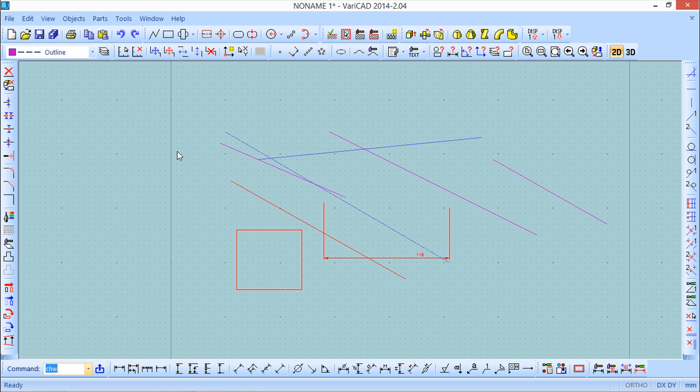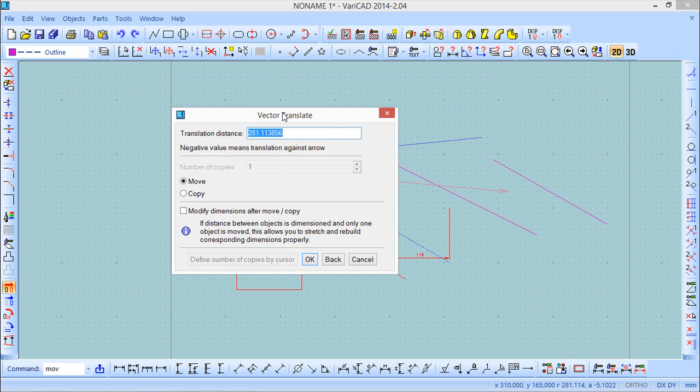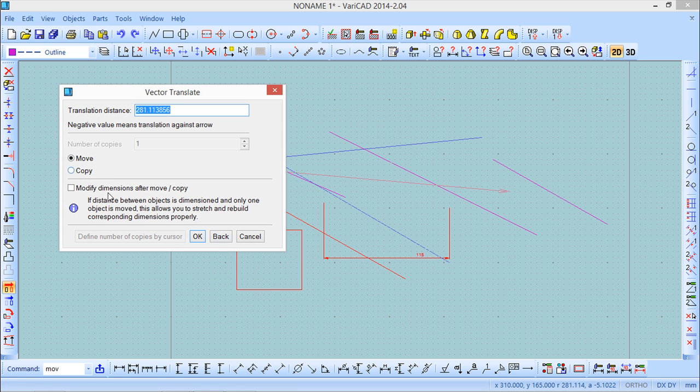But the purpose of this command, in fact, is that as layers are a possibility to organize information, worksets are another possibility. So let us try to do something that we still did not see, which is the translate command, but to choose the objects, instead of making an individual selection, by a workset. So I will do the translate, and on these options here, not this one, sorry, I will select the vector. We will see this a little further ahead in the lessons. Okay, and I will do a move or a copy.